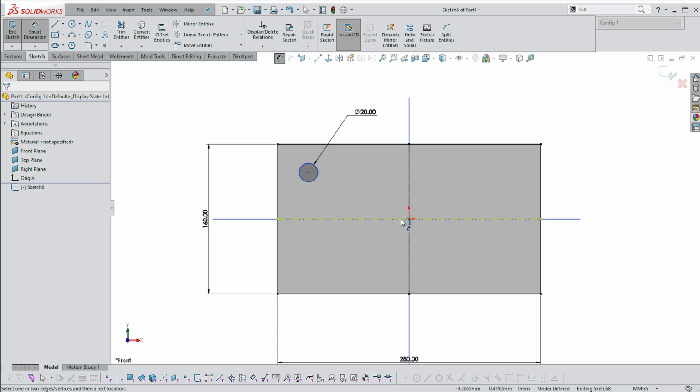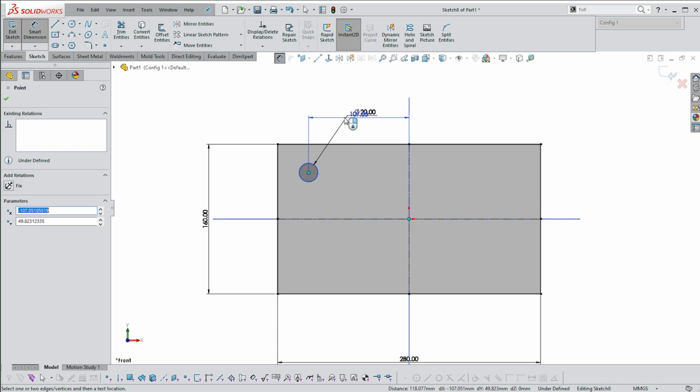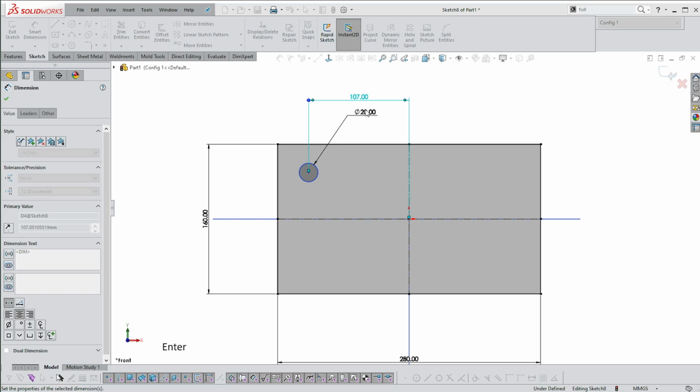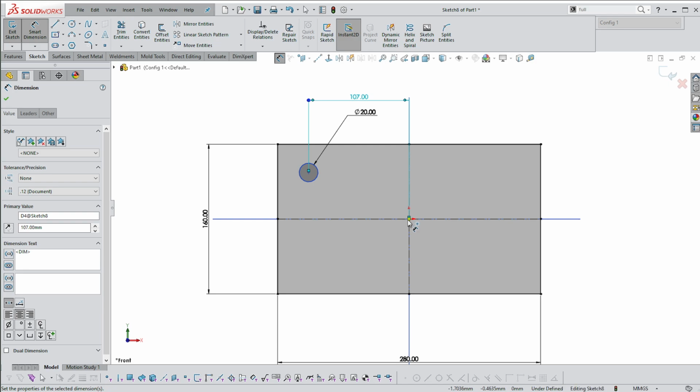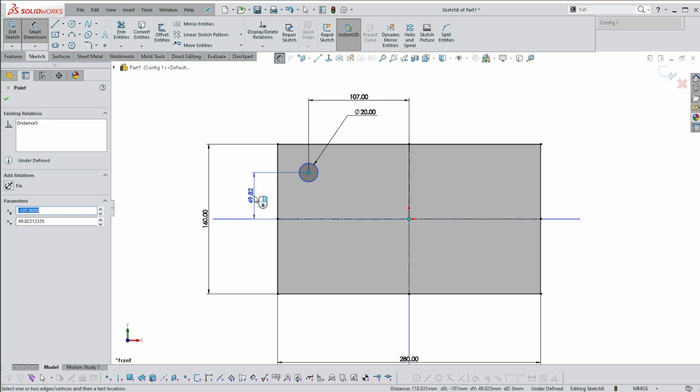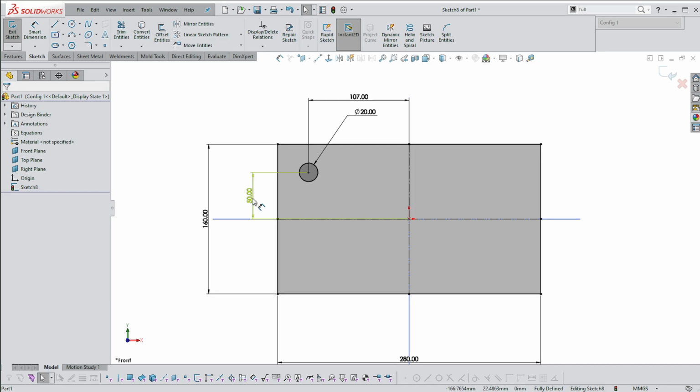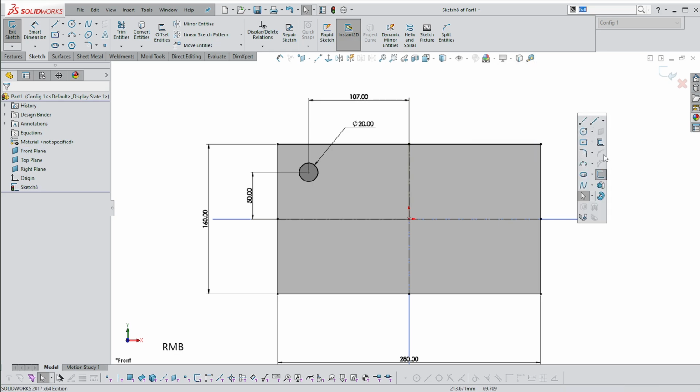So the first position dimension, and you're always going to want two position dimensions. Well, mostly you are going to want two position dimensions, but we can see what happens the moment we put the two in. Solidworks has it as fully defined, right? So it's working on the same principles as you would be working on regarding datums. So it's fully defined once the origin allows you to position this item. So let's just do that with a rectangle.